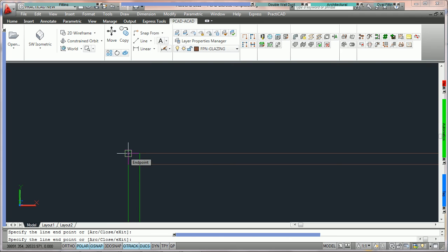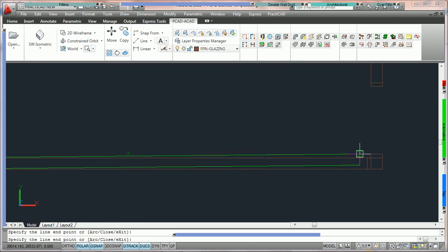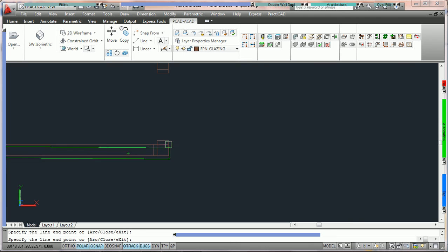We're going to click on this corner, and then we're going to turn the wall. And we're going to stop right here. Now to stop, and pay very close attention, what we're going to do is click one last time. And to stop the custom wall from moving, we can hit enter or we can right click and hit enter. And it's going to stop the wall at the last turn. And that's basically the last click.